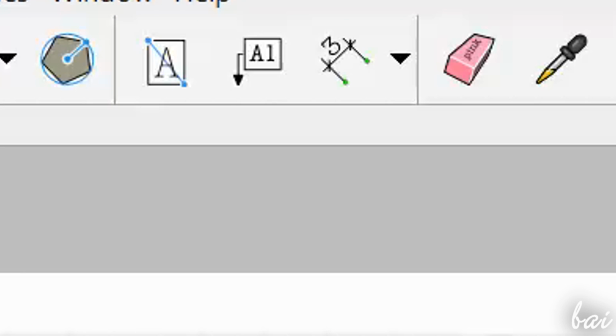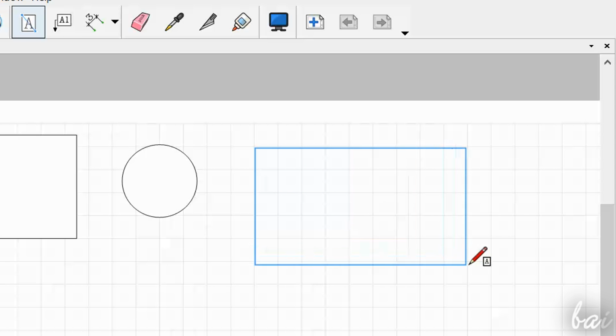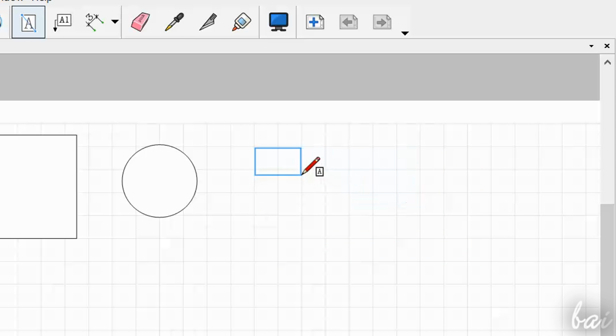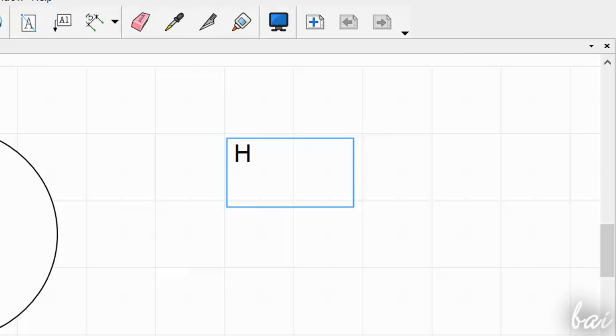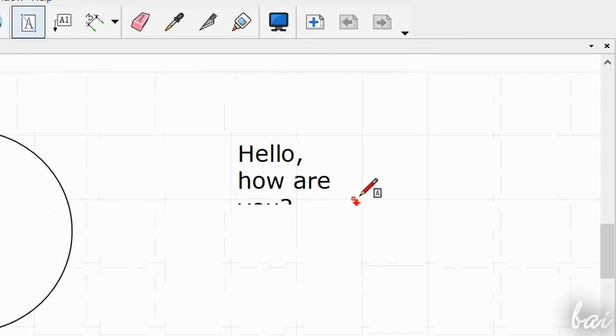There are also tools to add text and annotations. The Text tool adds pieces of text on your project. Just click and drag to define a text contour, which is used to define the space available for the text. Then type inside and click elsewhere when you finish. Make sure to have a text contour big enough, otherwise, your text content won't be shown in full.